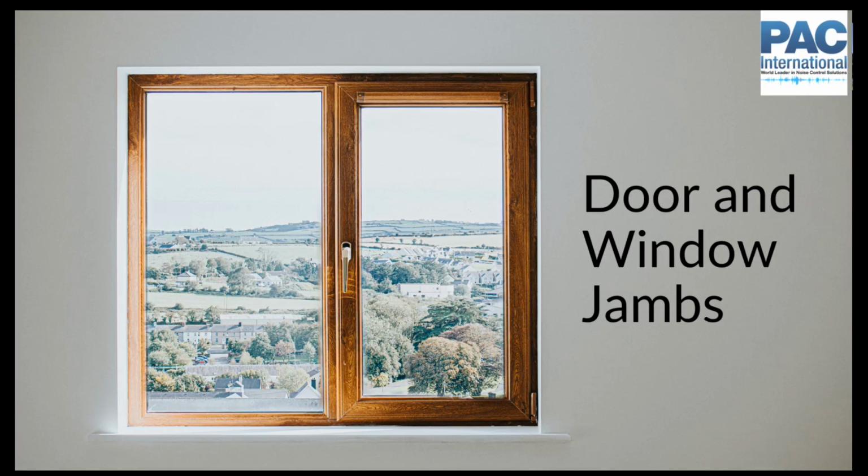But typically, an exterior facade of a building overlooking a highway or something like that, maybe we'll go for a higher performing wall, and we'll try and minimize the size of our windows, which often is at odds with daylighting requirements and views. So there's a push and pull there. We try and minimize the size of the windows because highly acoustical performing windows are very expensive. But then maybe we have clips and hat channel for our walls. We need to figure out that interface to the door or the window.